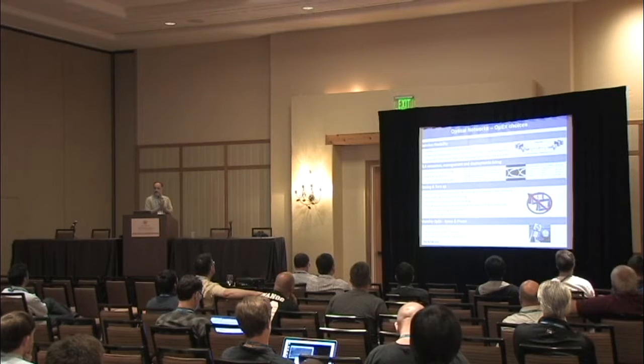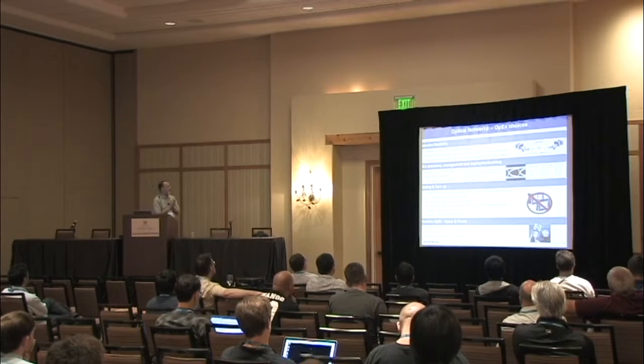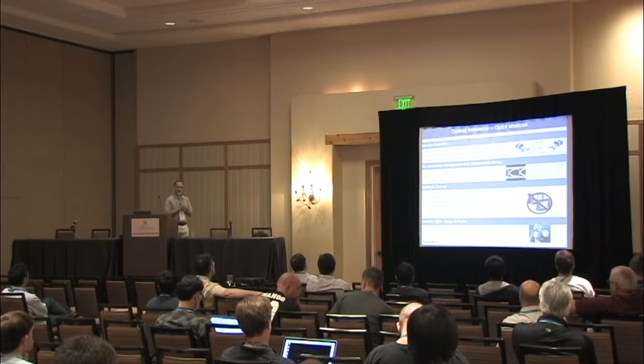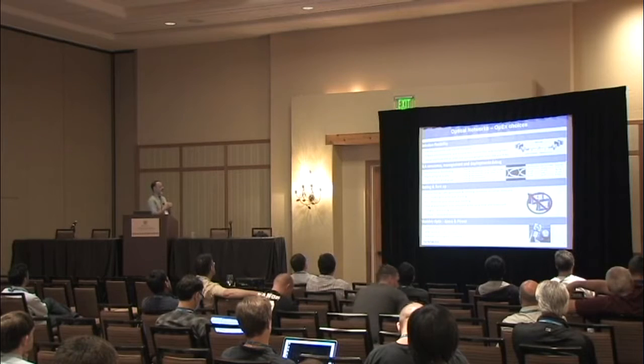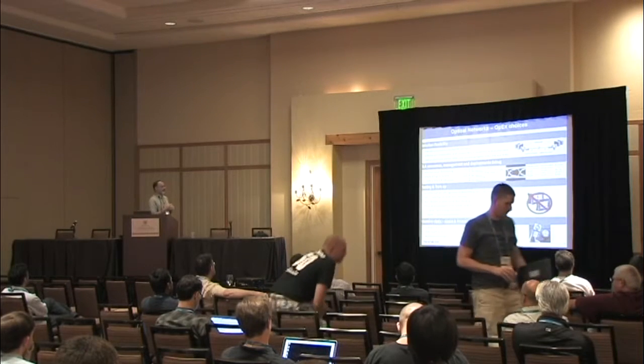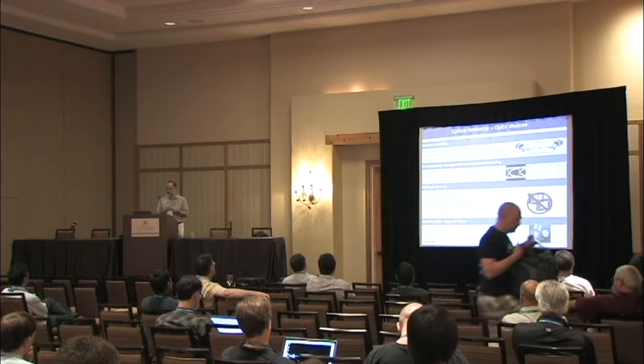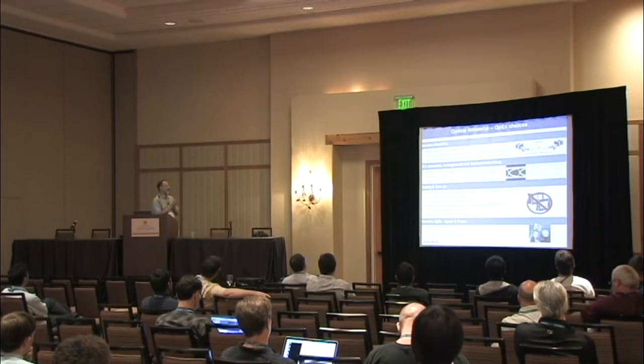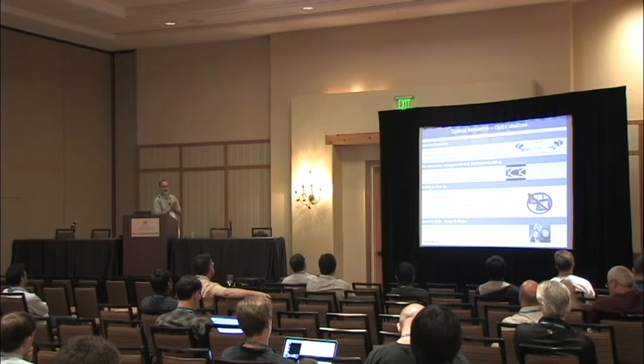It's going to cost a little bit more. Finalizing, going back to the simplicity. When you look at do-it-yourself of this type of networks, look at the capability to implement from the simplest to the highest, from media conversion to DWDM. It's interesting to have the same elements doing both converters and multiplexers and transponders and Muxponders, not different tasks. Look for adaptability from 10 gig to 100 gig and look into the future. 200 gig and 400 gig are probably a few years away.